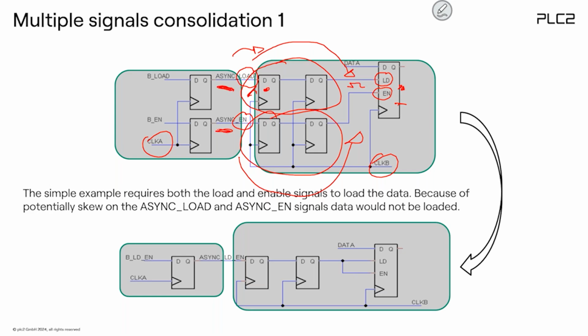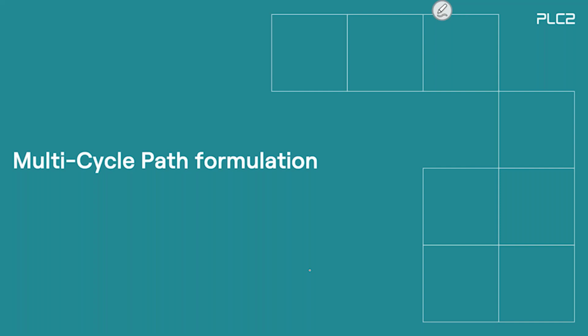Even a very, very small skew on the signal will lead to an error. So in this case you should take some precautions: combine these two signals into one single signal and then split it apart over here. This is the first one, this is the second one. This means it's time demultiplexing. Very simple example, but you need to think about this, because otherwise it will not work.